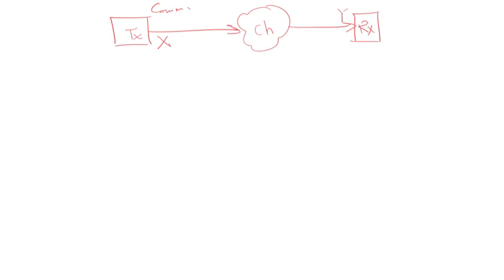Now, in this case, ideally, what do I want? Do I want h of x given y to be a large number or a small number for a successful, good communication? What's the objective of a good communication? That by reading y, I know x correctly. That's the objective of a communication system. When I receive y, I will be able to figure out what x was. If I want this, then I want h of x given y to go down. Zero is the ideal case, but generally, I want it to be reduced as much as possible.